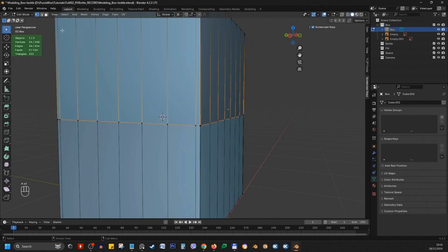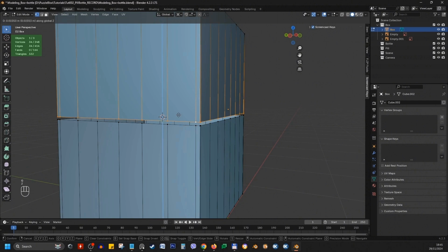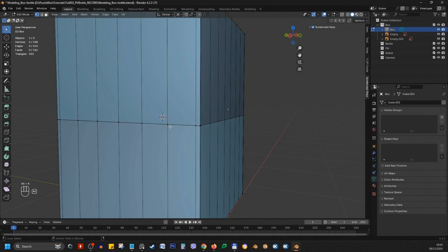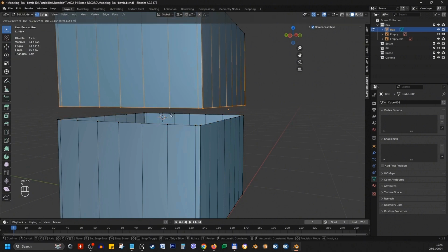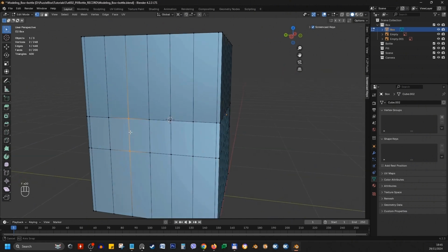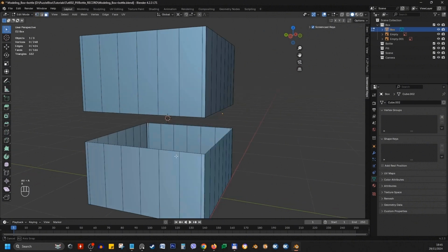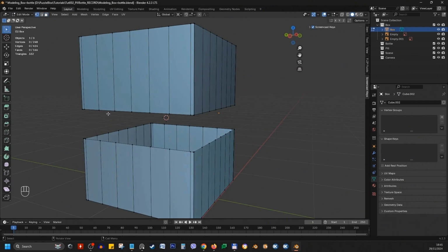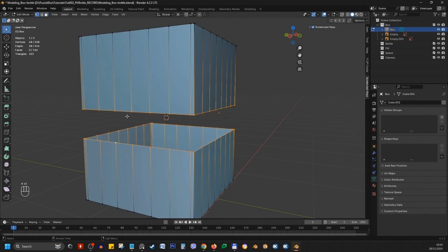Now all of these vertices are in the same location, and this is not good. We can join them in a few different ways. I can either select these four, add in a face, then select this edge and hit F until they're all connected. But I don't want to do this. Go into Face Select, while holding down Shift and Alt to select all of these, and X to delete all these faces. Now I want to use Loop Tools, which is an add-on that if you don't have activated already,